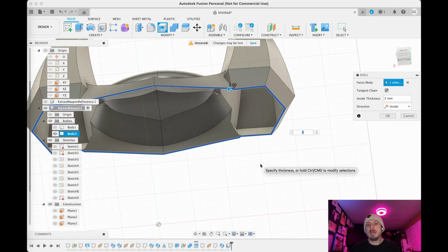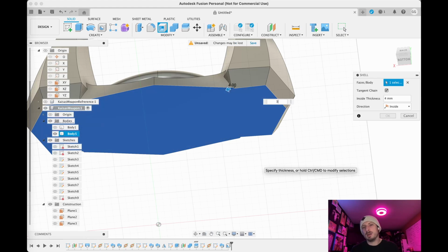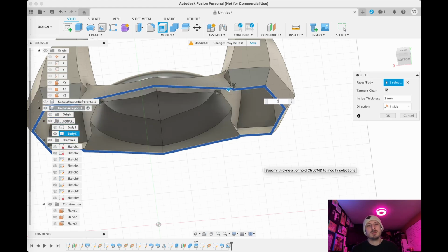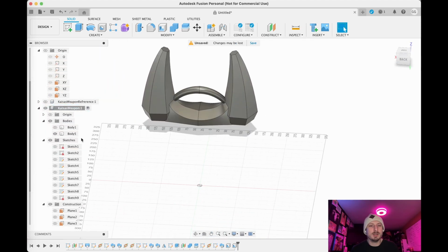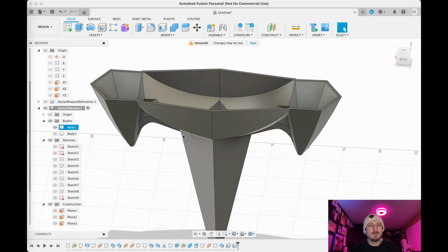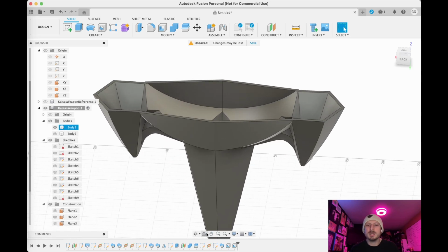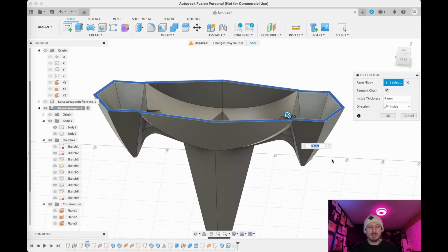Okay, so it did make it better because we could split at 2. We could split at 3. We can't split at 4. I think 3 is still good for security, and it would be better for LEDs. So I'm going to stick with that for this tutorial. But if I really wanted it to be 4, I would again adjust that offset plane to be at a different height where some of these intersections between the edges of the weapon aren't interfering with that shelling.